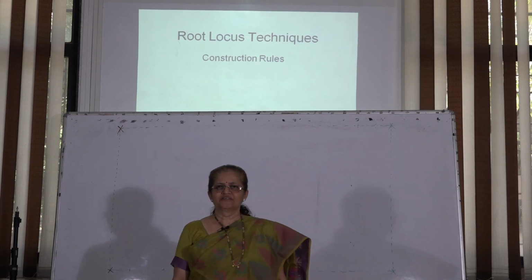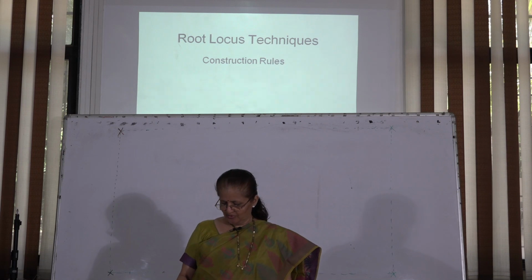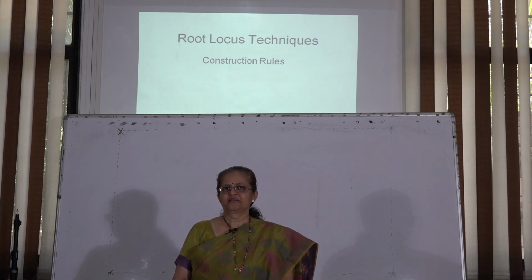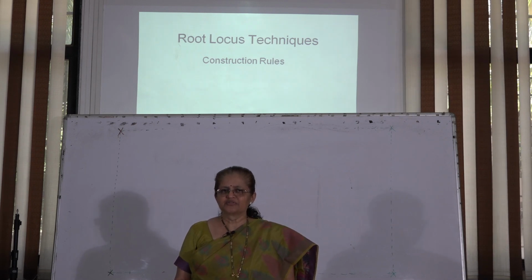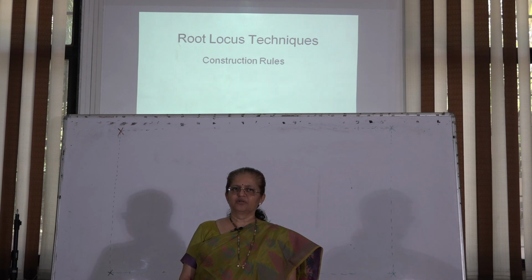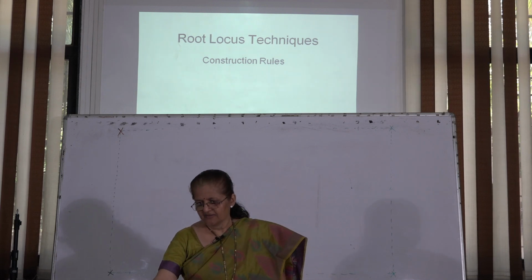Welcome to this lecture. In the previous lecture, we have seen the root locus concept. In that, we have seen that the transfer function we require is used in the pole-zero form. So, if it is in the time constant form, you have to convert it to pole-zero form and then use it.